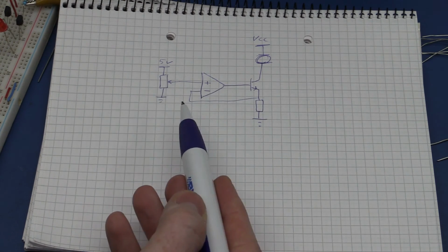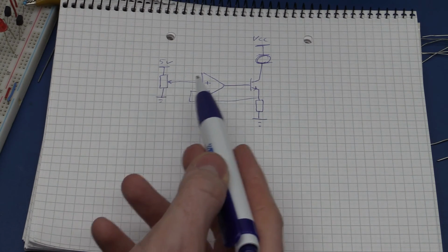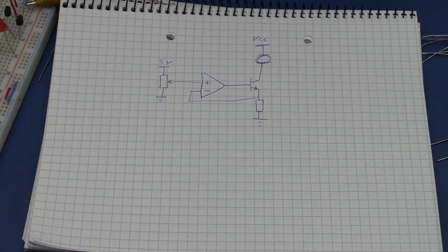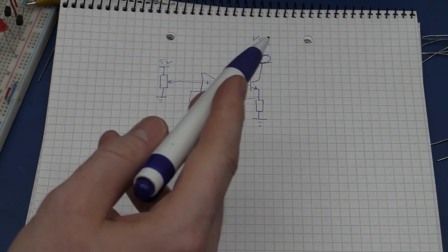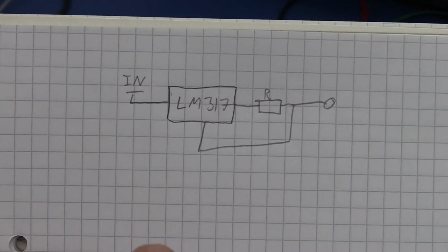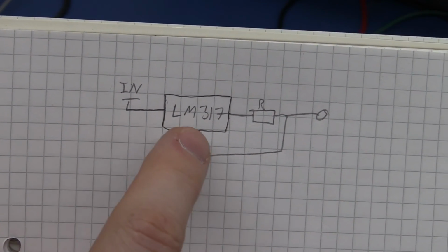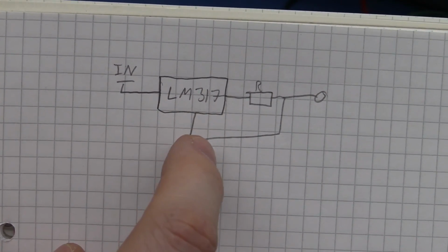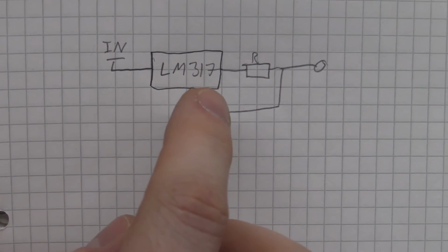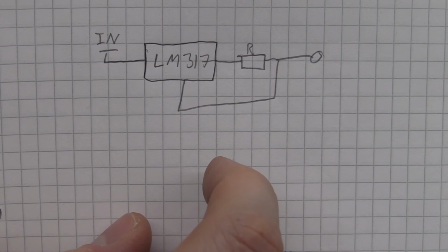And you can use this to make a constant current load if you want. And it can be used as a constant current driver for an LED, or a motor, or whatever you want. And I guess I have to mention it, there's always the classic one using the LM317 voltage regulator. We can kind of abuse the way that it's regulating to make it into a current regulator also.